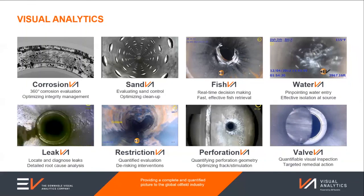And that way we can get to the area of interest with the minimum amount of risk, get typically good pictures as a result, and then pull back out of hole. If we then want to go further and we're happy that the environment is safe, we can put the centralizers back on and continue as planned. So really it's 100% dependent on the application, but for the most part, we will run centralized because it does give us the optimum viewing conditions.